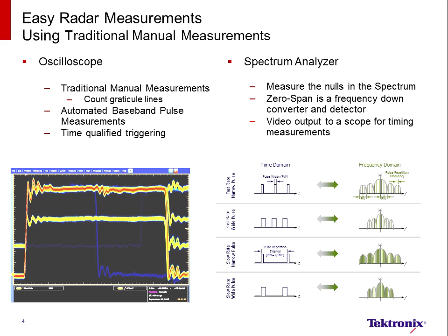By using compute power, automated baseband pulse measurement routines have been added to the oscilloscope, but while these measurement routines work very well on baseband pulses, they do not perform as well with RF modulated pulses, since the oscilloscope must trigger individual cycles of the RF burst. Identifying the exact time domain measurement points, such as 50% rise and fall positions, is very difficult.